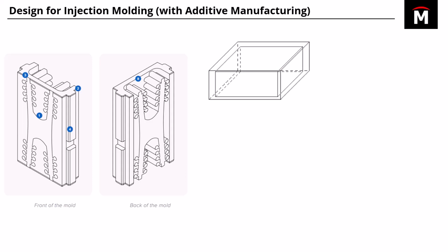Another thing to consider is scaling the physical part itself. So in CAD, and obviously it heavily depends on the material, but say for that high flow or high temp flow, low viscosity polypropylene, you'd want to scale that by like 2%. So you have your mask strap in CAD, scale it up by 2%, and then do your Boolean cut operation to build the mold itself. And that's just to counteract any shrinkage of the material post mold.